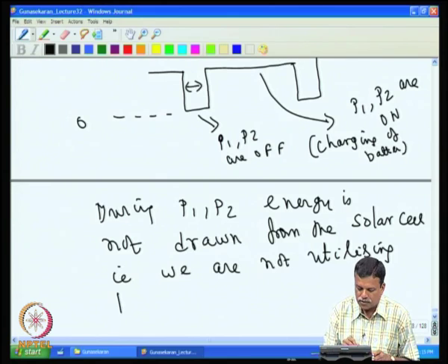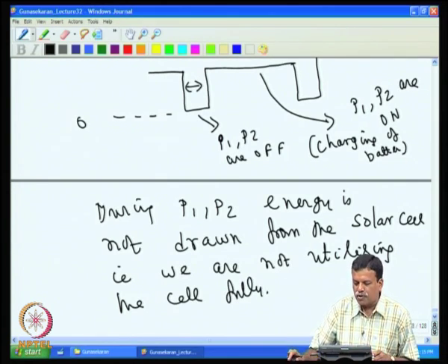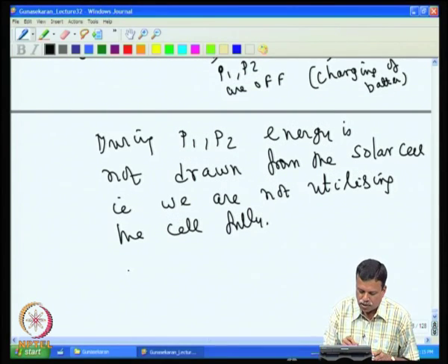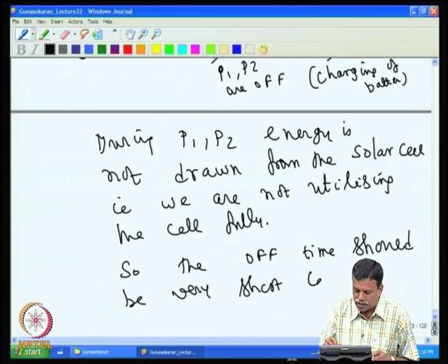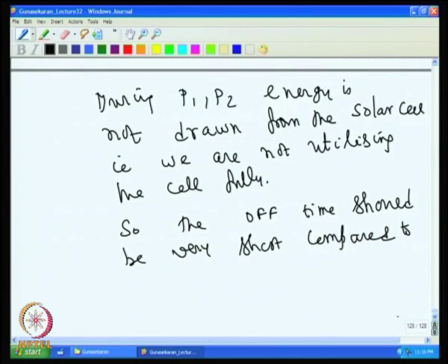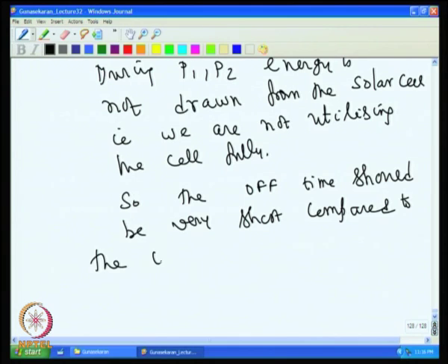So, the off time should be very short compared to the on time. That is why the ADC must be very fast.